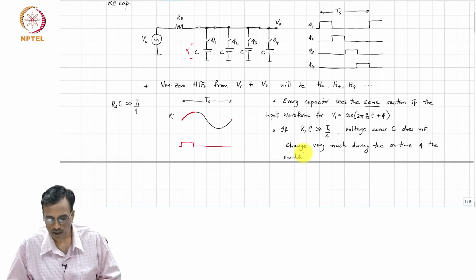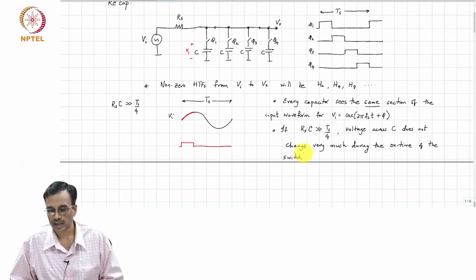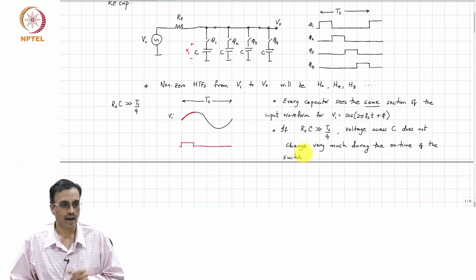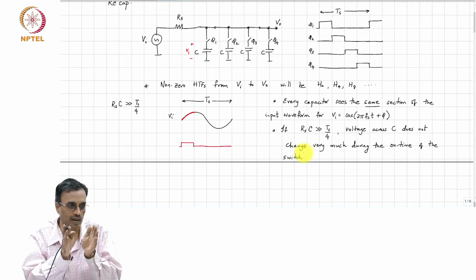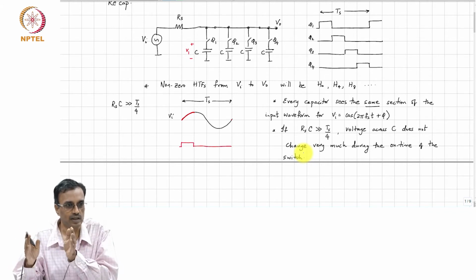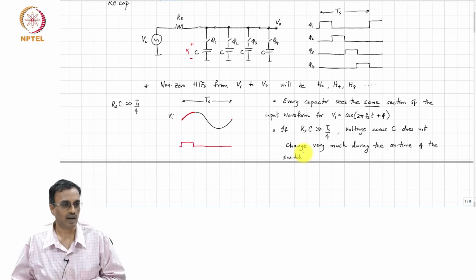Right. So, therefore, you can see that the voltage across the capacitor will build up to a large value as long as the input is at F_s or close to F_s, right. If the input deviates significantly from F_s, the current going into the capacitor in one clock cycle corresponds to one section of this input sinusoid. During the second clock cycle, it corresponds to some other section of this input sinusoid. So, on average therefore, the voltage developed across the capacitor is very small, right.